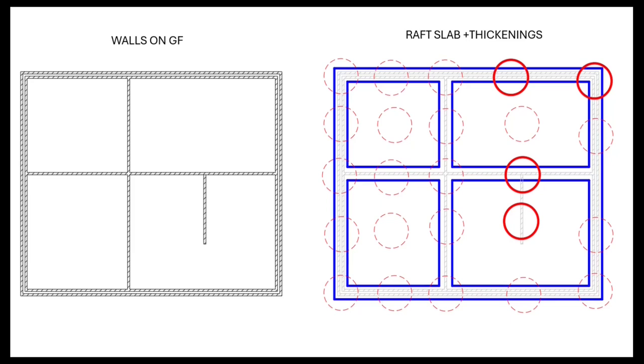Sometimes it's not easy to justify because we may have different arrangements. For example, for one corner, we may have single leaf walls with heavy loads. For other corners, we may have cavity walls with smaller loads, but there are also different eccentricities. So I would say in such a case, we probably would have to check more cases.